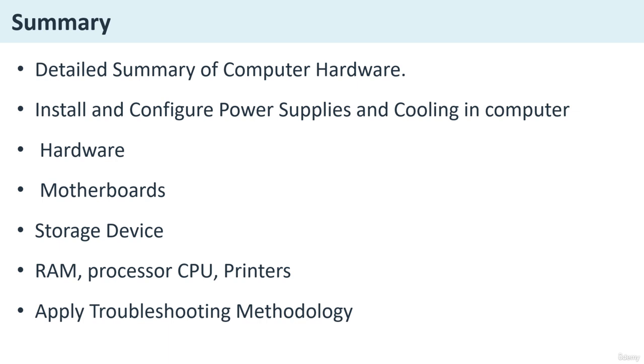Here I will also tell you about the power supply and cooling myths that are debunked. First of all, we think that higher wattage PSUs waste electricity, which is false. They only deliver what is needed. Second is that liquid cooling is always better than air. That is not always true because high-end air coolers can match an AIO. Third is that more fans always means better cooling. That is absolutely incorrect, because if airflow isn't optimized, whether you place 2 fans or 3 fans doesn't matter. So you have to optimize the airflow.